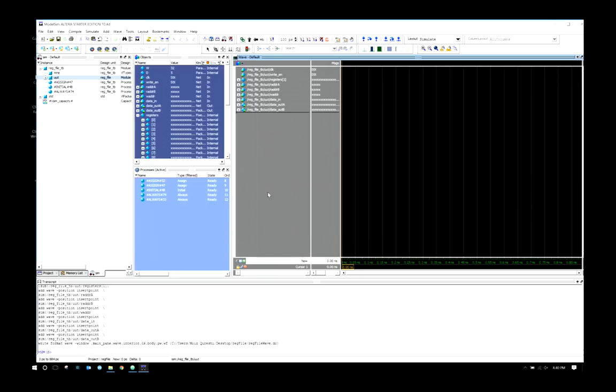So next time when I come in ModelSim, I can open that DO file by going File, Load, I believe? Yeah, Load macro file, and it's going to load back all that stuff. To run this, you have all these little icons. You have Break, Run All, Continue Run, Run, and Restart. What you're going to be using is just two of them.